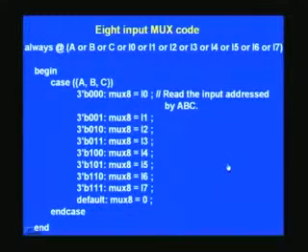So what you have seen earlier is a mux circuit, and this you are already familiar with. It's an always block with a begin here and end here. And now we have added one more statement called case here, which is very much close to the C case, except that this is actually hardware design, which you should bear in mind. And we have also seen a concatenation of 3 numbers here, and that's how we put them within brackets. This also is a mandatory thing.